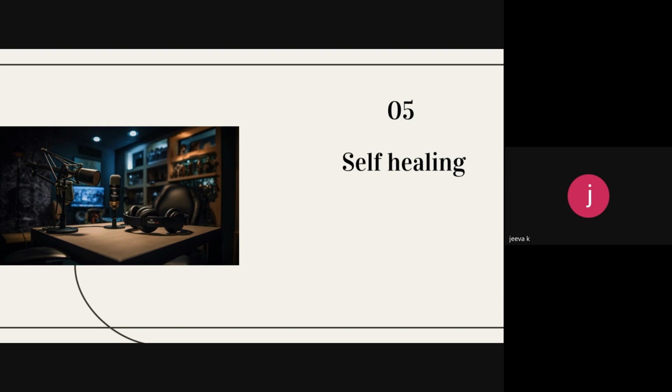So if he or she, that concerned organization, is using that frequency, and suddenly the licensed person becomes available for the next hour and gives information that he is going to use the same frequency, automatically, if this unit is connected with the software defined radio, it does not ask for any option. It automatically searches for what frequency is available, uses that bandwidth and frequency, and the output is given.